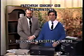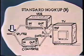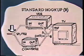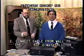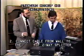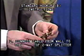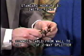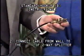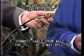We've got everything taken apart so that we have all of the parts right in front of us here. The first thing you'll want to do, John, is to connect the cable coming from the wall outlet, the wall plate in your home, and we've got a cable run inside here. You want to connect that to the input of the two-way splitter. Okay, here's the splitter and here's the cable. Now this does have to be fitted, and it's a screw-on connector. Okay, that's done. Nice and snug, right? Now we'll assume, too, that your converter is plugged in already and it's ready to go.